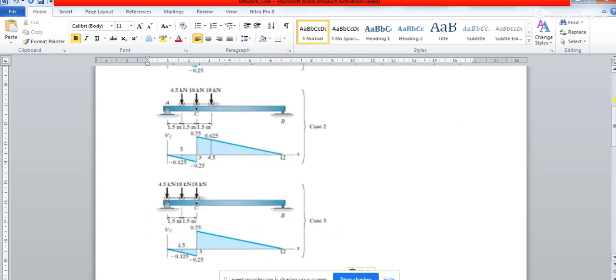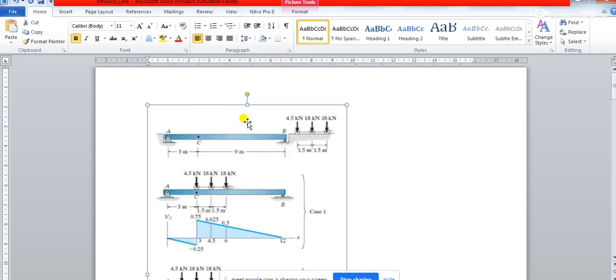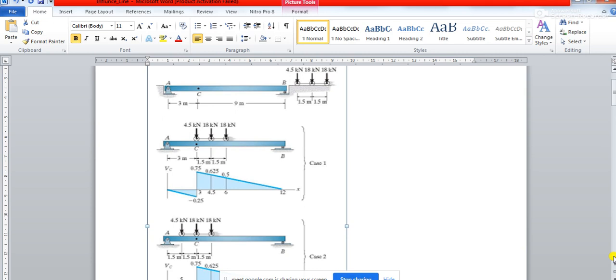See, this is the diagram, right? So you see, at this position the load has not entered the beam. What we have said is that because of the point load, whenever there is a movement of a series of concentrated loads, the loads must come to the maximum ordinate. So the first position, the case 1 position, will be this one. So you see, case 1 position of the load is this one, right?